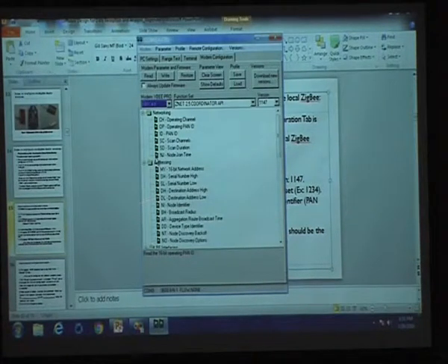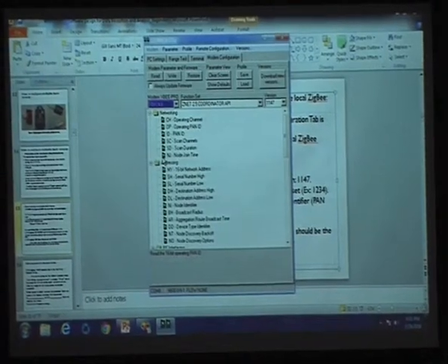So the XB24B modem has been selected. And what is the functional set? As I mentioned in the beginning, we are trying to use the API data transmission mode. API mode means we are trying to put data in a particular format. The frame structure we are going to create on our own.